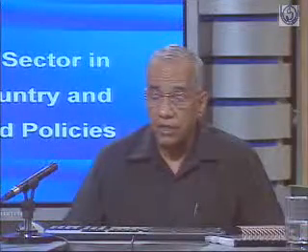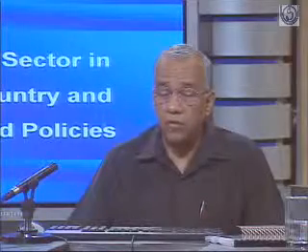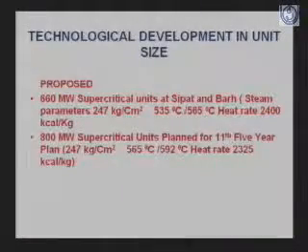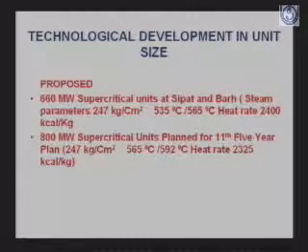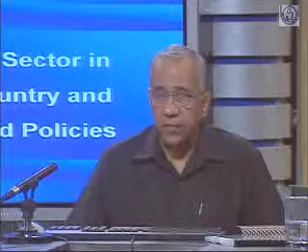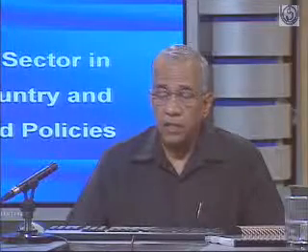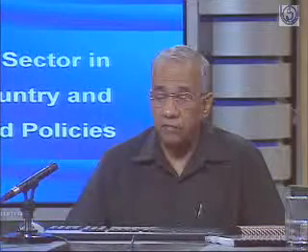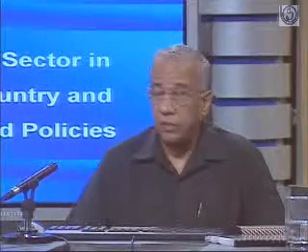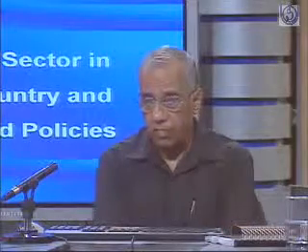And the heat rate number is now 2400 kcal per kg. So this is the heat rate, 2400 kcal per kilowatt hour. This is wrongly printed as kg. So it means for generation of one unit, instead of 3500 kilocalories, you need only 2400 kilocalories. That would mean that the coal consumption will be proportionately less, and these machines will give you higher efficiency, between 1 and 2%.